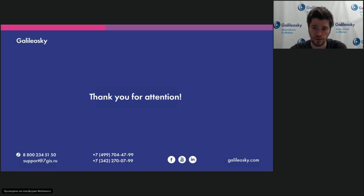Actually, our Galileosky 7 and base block are pretty good with working with the memory, but yes, if you're creating cycles or loops, it is very recommended that you use a delay element so that the tracker does not check each millisecond, because that negatively influences the performance of the tracker, and the device starts to work slowly or can even crash.